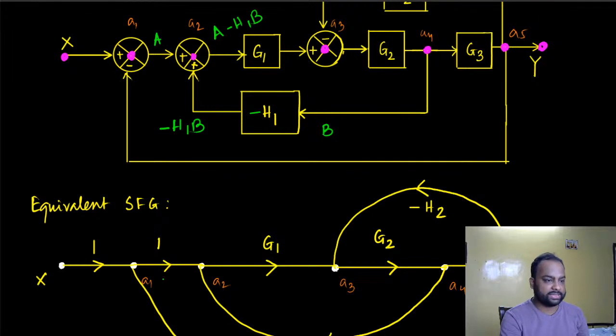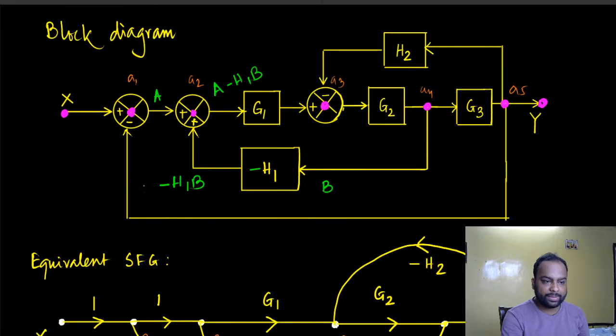That is the mystery of the minus sign, right? And the same thing happens with all the negative feedbacks. Whenever we have a negative sign, we pull that negative sign out of the comparator into the transfer function itself, so that the comparator essentially becomes a summing block.